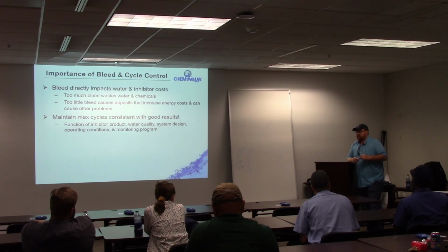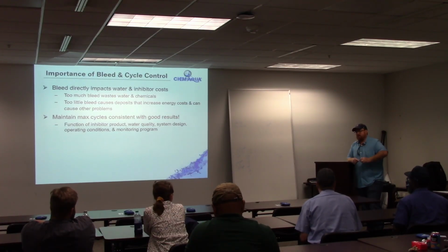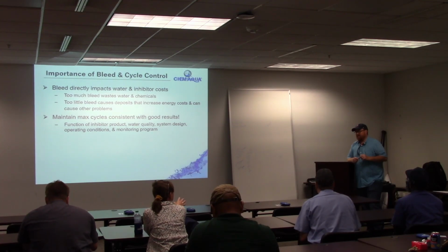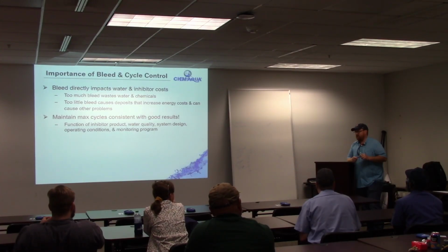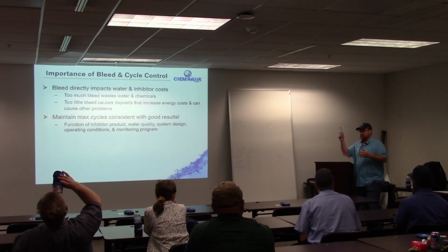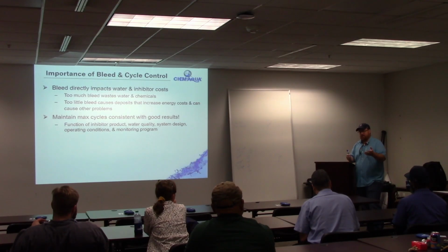Do you find that your conductivity is staying at set point, or is it continuing to climb even though it's blowing down? No, it's dropping. It's dropping? Okay. So does it go below set point? Only in the winter, it seems. Okay. But during the summer, I noticed that it's not blowing down. Yeah. During the winter, you're not going to have nearly as much blowdown. It seems like so much makeup water. Yeah. So makeup is whatever you're losing to evaporation and blowing down, that added together is your makeup.